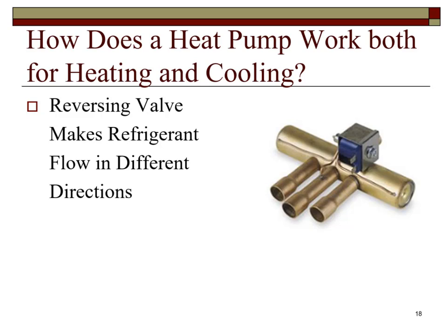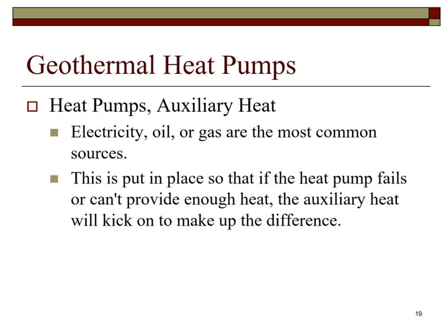It's worth noting that a heat pump can also act as an air conditioner because of the reversing valve. It sends the refrigerant first from the compressor to the outdoor coil in the air conditioning mode and to the indoor coil first in the heating mode. Heat pumps must have an auxiliary means to heat just in case the heat pump fails.